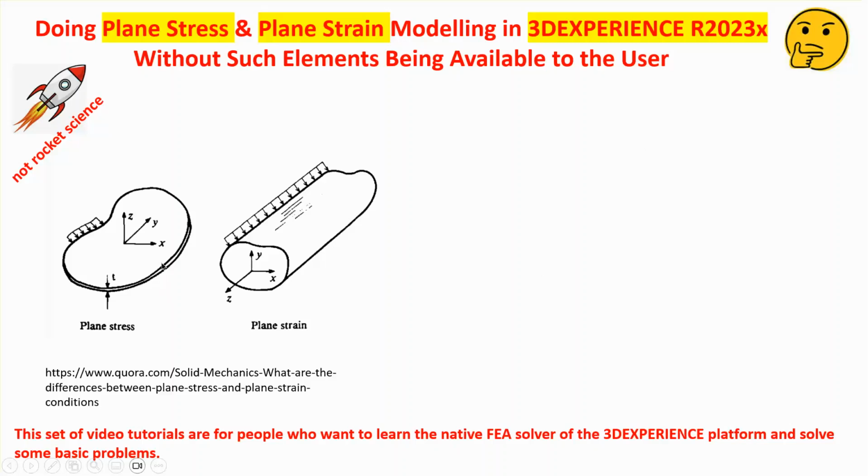Let's recall what actually a plane stress problem is. Imagine that you have a sheet metal that is loaded in its own plane. Then there is very little stress through the thickness direction, and that's why we say the stresses are zero, and that's what the plane stress condition is. On the other hand, if you have a long structure, such as an earth dam, and there is maybe hydrostatic pressure behind it, then the strain in the axial direction, in this case the z direction, is zero, but the stress is not. So that's the plane strain condition.